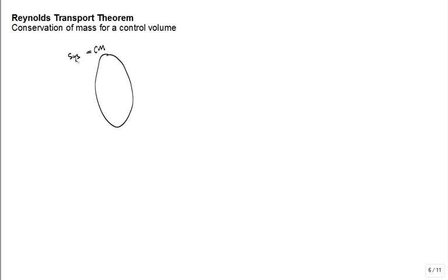All right. Now, that's at time T. Some later time, it's in a flow field. It's a very general system, very general flow field. It goes, and it's now there. That's at time T plus delta T. This is the standard derivation of the Reynolds transport theorem. So this is my distorted system, my closed system, my control mass at the new time, T plus delta T.